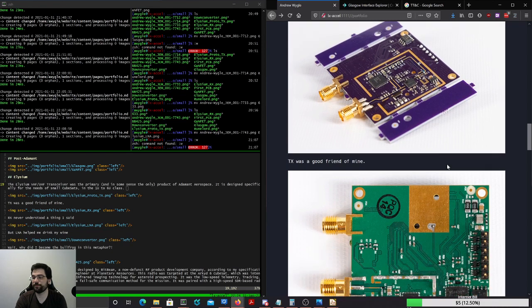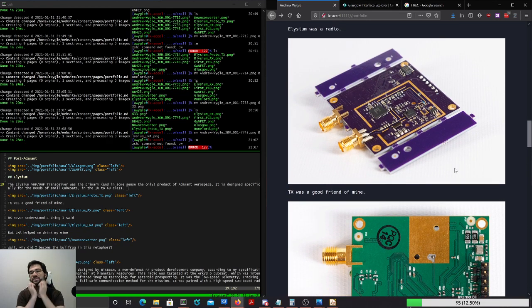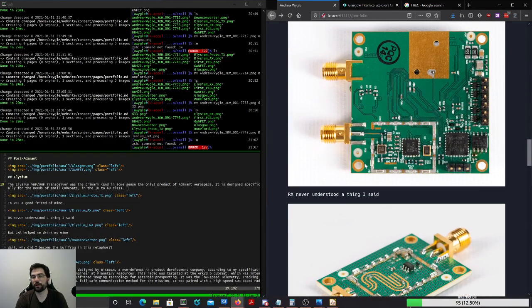Basically, the design constraints here were this: small CubeSats, 1U to 6U, that range, are often very power limited because they're small, and it means they only have so much area for solar panels. So the primary driving consideration here was power consumption. The receiver side, which is down here, can support sitting around waiting for a signal to arrive, drawing 25 milliwatts or less of power.